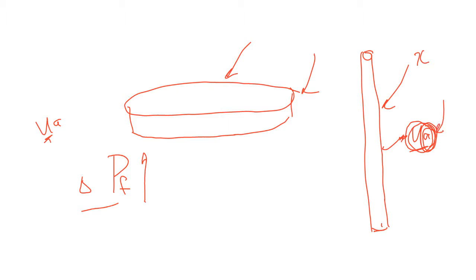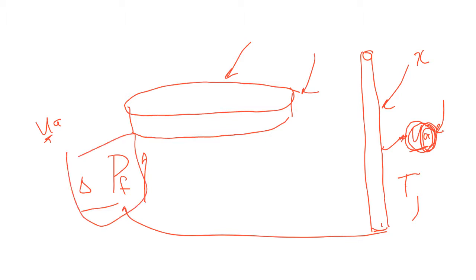But the fact that I can play with the temperature has a much bigger effect than the pressure losses. I cannot tolerate pressure losses that affect the sizing of my equipment when I have to drive the fluid through it. I need to take cognizance of the effect of pressure drop, but generally it will not be the game maker when I make decisions. The game maker will be the heat transfer.